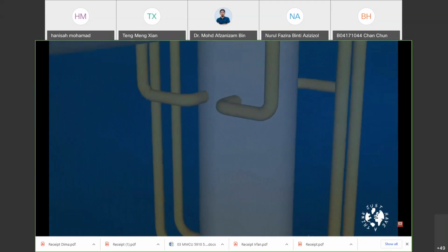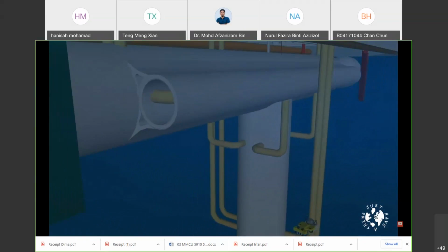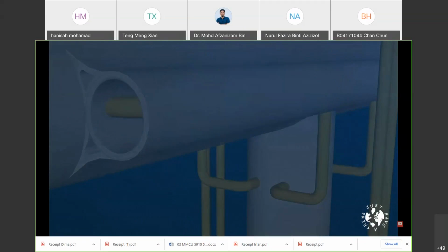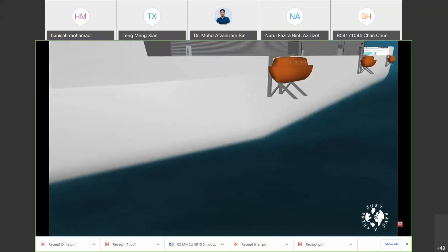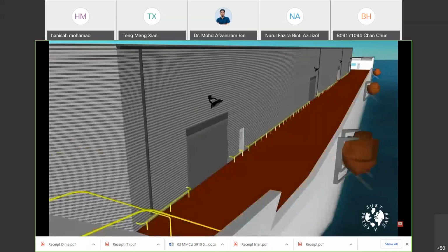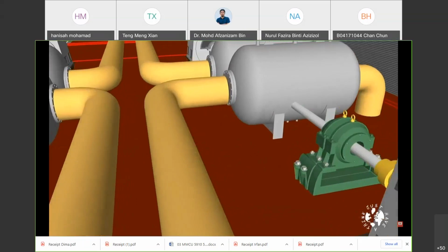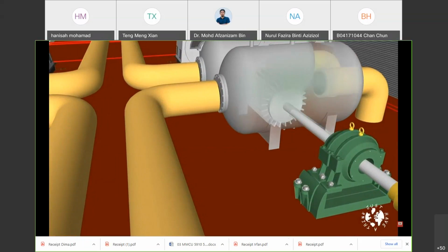But as the fluid flows upwards, it's drawn into evaporators that are bathed in the warm surface water. This takes the temperature of the Freon above its boiling point, and that means a change in state from liquid to gas, which in turn causes an expansion and kinetic movement. The gaseous Freon now takes the course of least resistance, which sends it through the pipework up onto the top of the platform and into the electricity generation plant, where it passes over a turbine, which in turn drives an electrical generator.